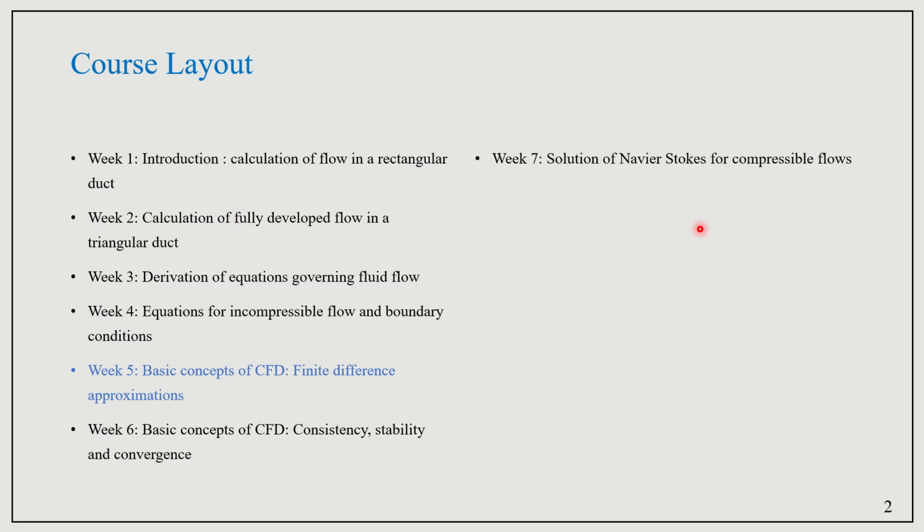And till now we have seen what all the equations governing the fluid flow are. Mostly the equations we will be solving when we are using the cold flow system are mass conservation, that is the continuity equation, and the momentum conservation equation. So altogether, if it is a 3D system, we will have 4 equations. And in addition to normal cold flow, if any other energy exchange or reactions are taking place, we solve additional equations based on that, like energy equations and species balance equations. Those things we have seen in the last class.